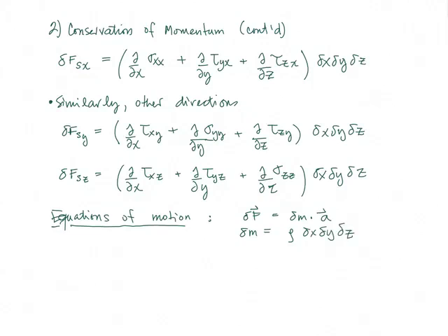And so, in the x direction, we have the weight, which is rho g in the x direction. We don't assume that g applies in any direction yet. We're going to divide over by dx, dy, dz everywhere, so I'm not going to write it down because it appears in every term, plus the surface forces in the x direction.